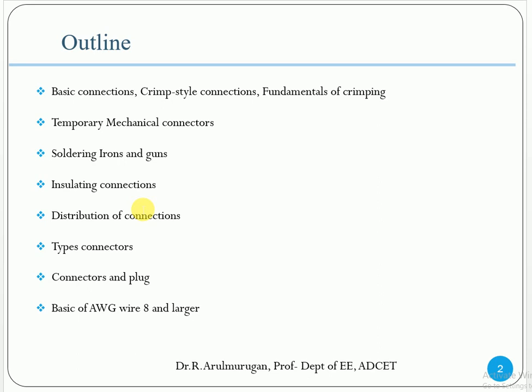Similarly, the wire, okay, the wire helps in passing the current. Okay, it is helping with distribution, from the generating station to the consumer, distributing the current. So how are you going to distribute it? How is the tapping done? For example, I told you in the room, every load needs phase and neutral. Phase and neutral are needed. Phase is taken from the switch box, the power supply.